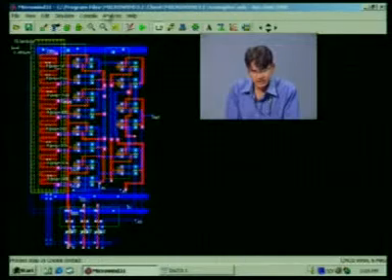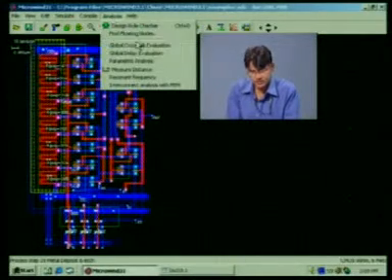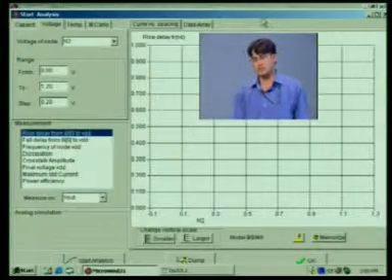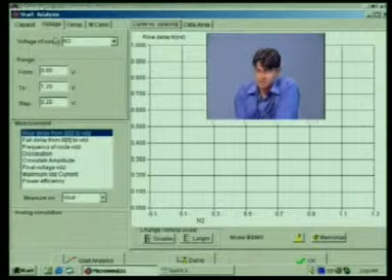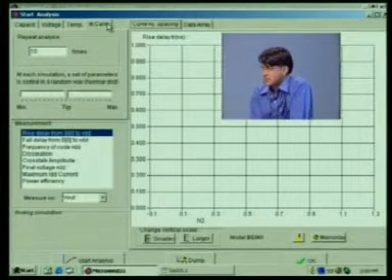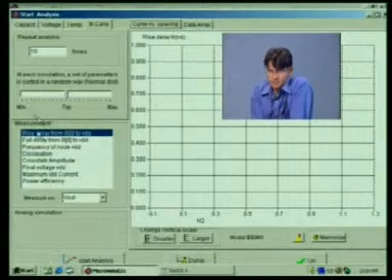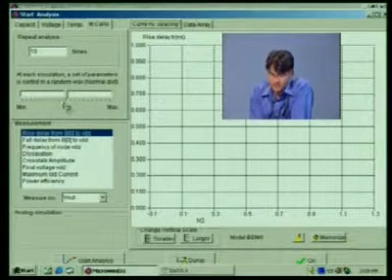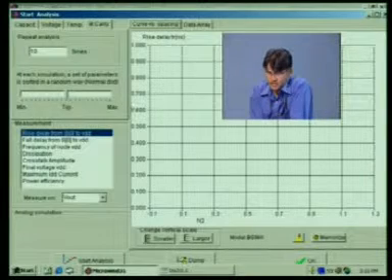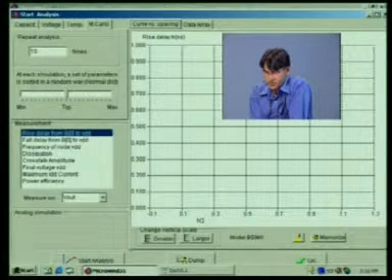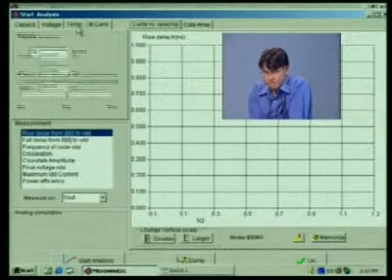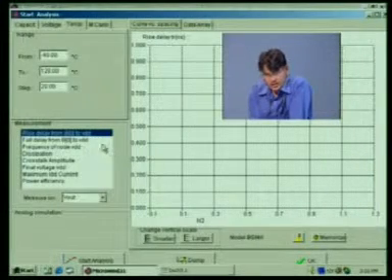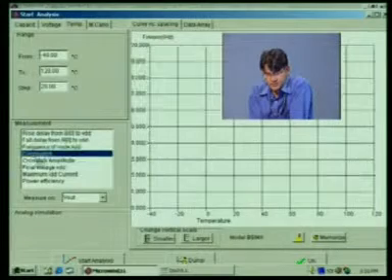And there are analyses. One analysis is called parametric analysis. I will show this one, just double click this. This analysis, similarly Monte Carlo analysis, statistical analysis, you can give the number of statistic values, like suppose you want 10 values, for 10 times you want the output temperature, you just vary the temperature, give the step size, and these are different kinds of analysis possible here.